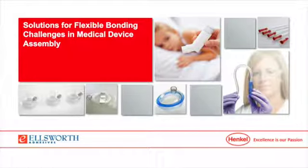So a couple of key things that we do remind our clients and partners with regards to biocompatibility tests. It is the fact that the adhesive must be fully cured. So any submissions that Henkel or any adhesive supplier does to an outside lab like Toxikon or NAMSA, it's really critical that the adhesive be properly and fully cured. In the case of Henkel, we do what I would consider to be a worst case test. In many instances, we're actually testing the bulk adhesive, and by that I mean if we can, we will actually cure a film of adhesive.